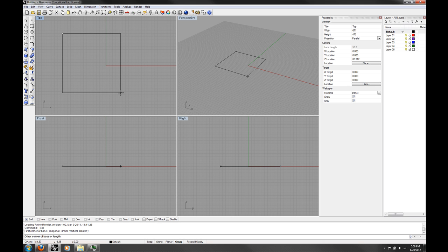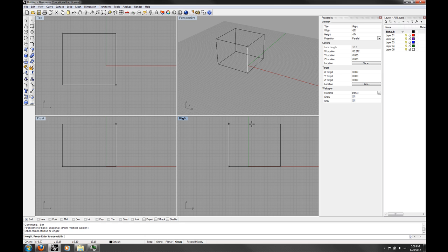And the perspective viewport will show you what it looks like in 3D. So if I'm starting from the profile of the cube, top view may be a good idea. So I can use top view, and then I can click. And then I can move up and down in, let's say, the front view or the right view, because that's giving me a good way to tell the depth of what I'm doing. The top view doesn't show me that, but these other views do.